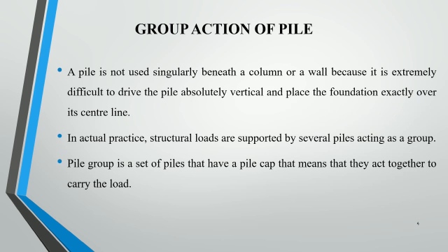Group action of pile. A pile is not used singularly beneath a column or wall because it is extremely difficult to drive the pile absolutely vertical and place a foundation exactly over its center line. In actual practice, structural loads are supported by several piles acting as a group.